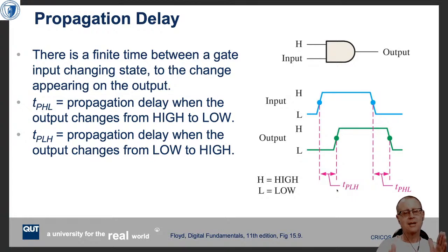If there's a way through your circuit where the two inputs of one device have very different propagation delays getting to that device, then you will get glitches. We need to talk later about how to deal with that. The simple fix is to equalize the delays. You make sure that you always get the same amount of delay.